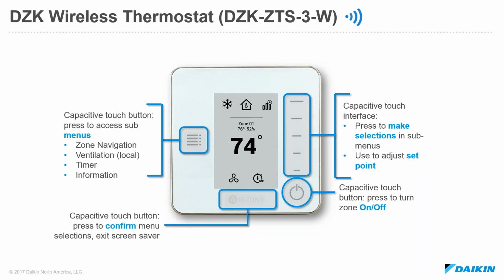If you tap in the top half or tap in the bottom half of those graduated lines, it allows for really finer control. So there's single digit increments, 74 to 75 to 76. So tapping allows for that single adjustment of set point. Swiping will generally jump 4, 5, 6 degrees as you swipe up and down on that capacitive interface.